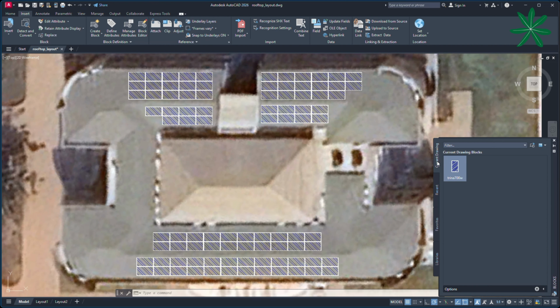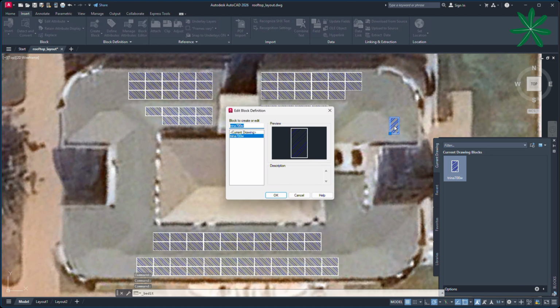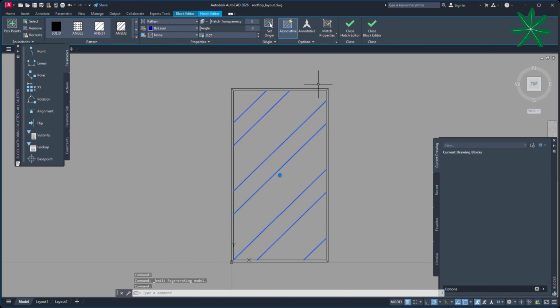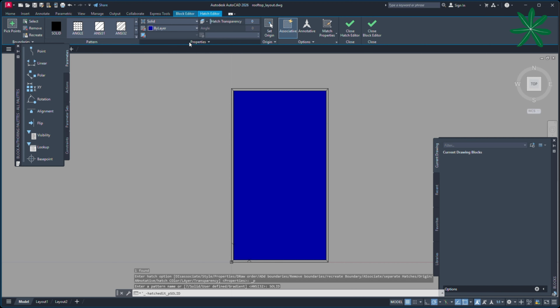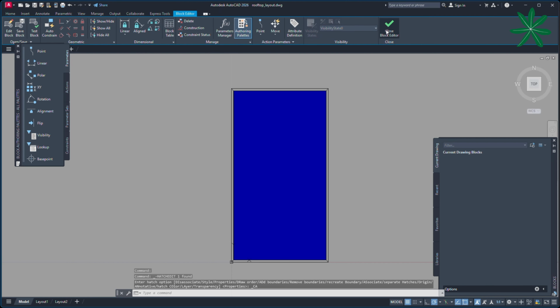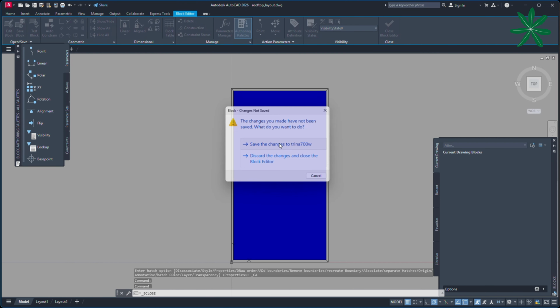You can see that where we are right now, we can't really see the cells. So let's change the hatch. Let's use the block hatch. Let's change it from the angle to solid. Then let's see how that will affect it. Good. This is more visible.